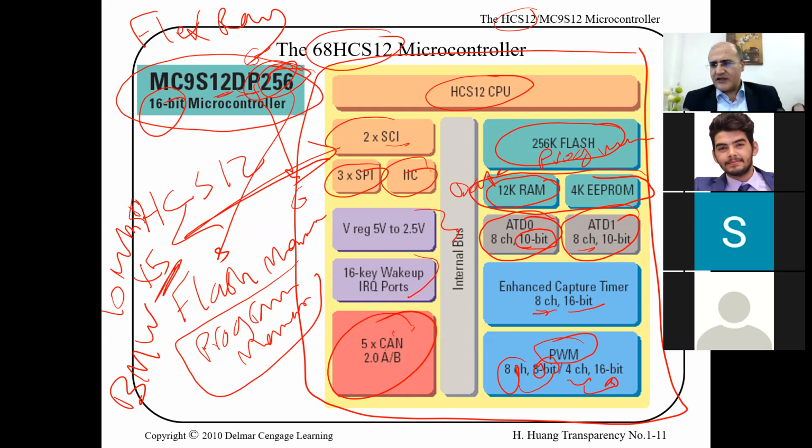It has many security issues. Today the data on the CAN bus is still raw data. That's why a few years ago they hacked a Jeep Cherokee on the highway. Somebody was able to get the message ID of the brake. We're talking about brake by wire.